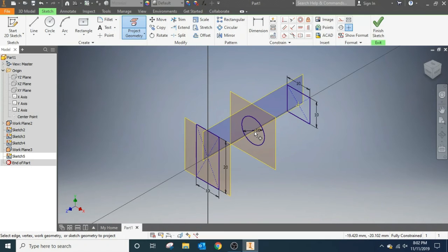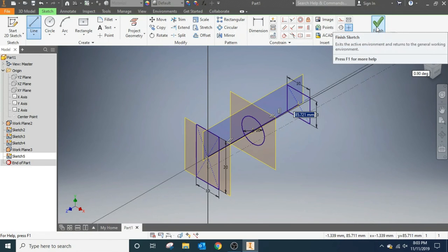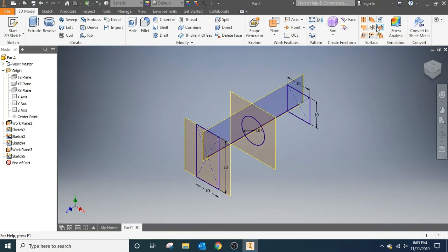So if we did this for this circle and this rectangle, we could pull this circle onto this plane in our other sketch so that we can reference it, we can make things tangent to it, that sort of thing. It's for placement. So I got that point, and that point, and now I'm going to go ahead and make a line to connect these. And there you have it. We have our line that is going to be used as our rail in the Loft tool. It's pretty simple. We're already almost done actually.